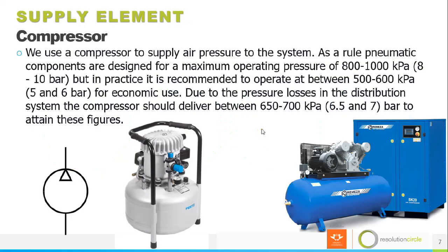Okay. In the supply elements, we have compressors, air service units, and gauges. What is a compressor? What do we use a compressor for? We use a compressor to supply air pressure to the system. As a rule, pneumatic components are designed for a maximum operating pressure of 8 to 10 bar, which is 800 to 1000 kilopascals.